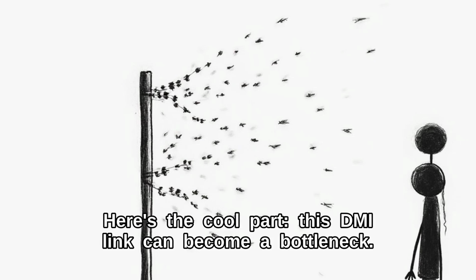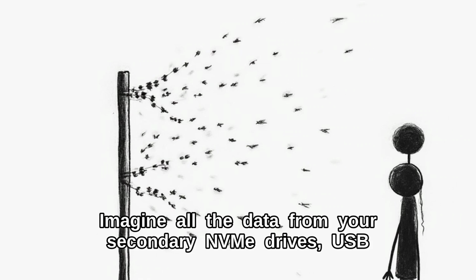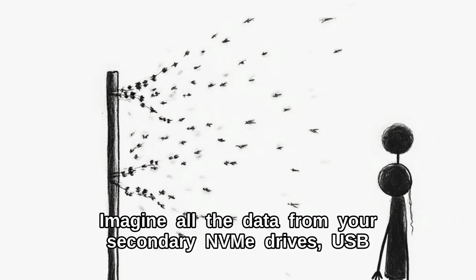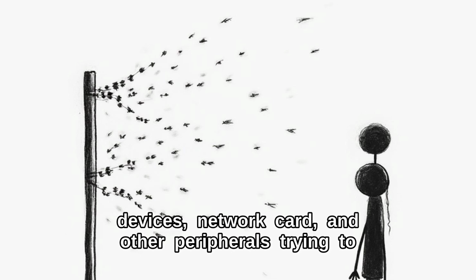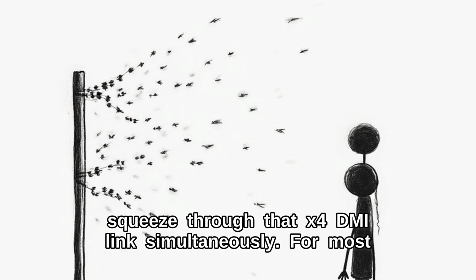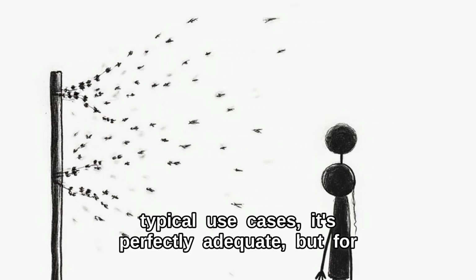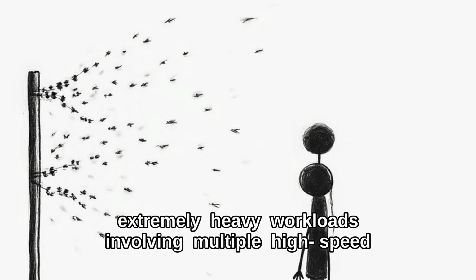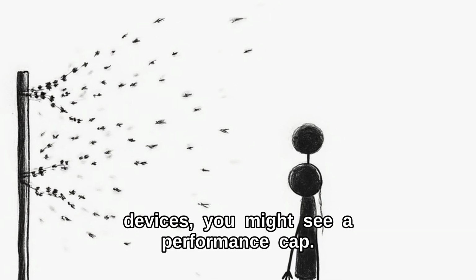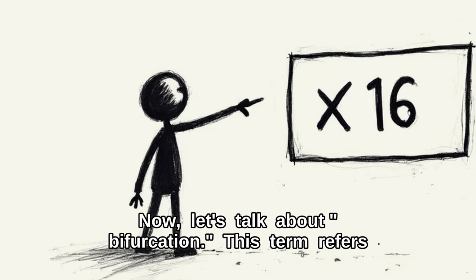Here is the cool part: this DMI link can become a bottleneck. Imagine all the data from your secondary NVMe drives, USB devices, network card, and other peripherals trying to squeeze through that X4 DMI link simultaneously. For most typical use cases, it is perfectly adequate, but for extremely heavy workloads involving multiple high-speed devices, you might see a performance cap.